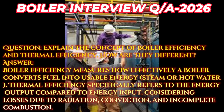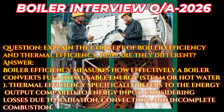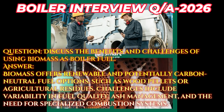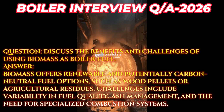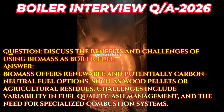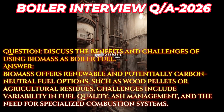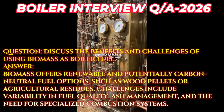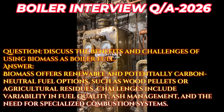Thermal efficiency specifically refers to the energy output compared to energy input, considering losses due to radiation, convection, and incomplete combustion. Question. Discuss the benefits and challenges of using biomass as boiler fuel. Answer. Biomass offers renewable and potentially carbon-neutral fuel options, such as wood pellets or agricultural residues. Challenges include variability in fuel quality, ash management, and the need for specialized combustion systems.